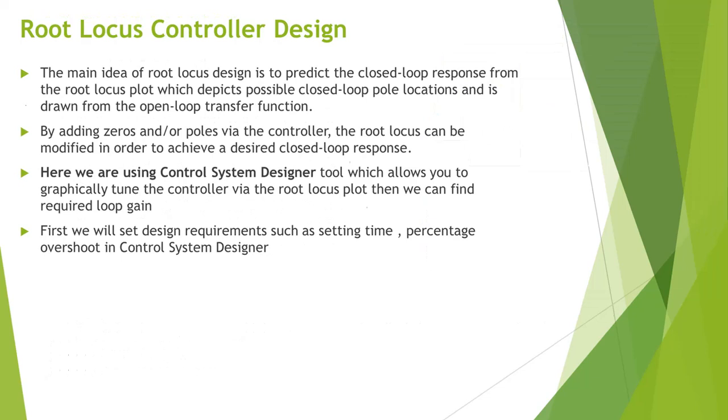After employing frequency domain methods for controller design, let's now employ root locus methods. The main idea of this method is to predict the closed loop response from the root locus plot, which depicts possible closed loop pole locations. We can add zeros or poles via the controller to this root locus in order to achieve a desired closed loop response. Using the Control System Designer tool of MATLAB, we'll set design requirements such as settling time and percentage